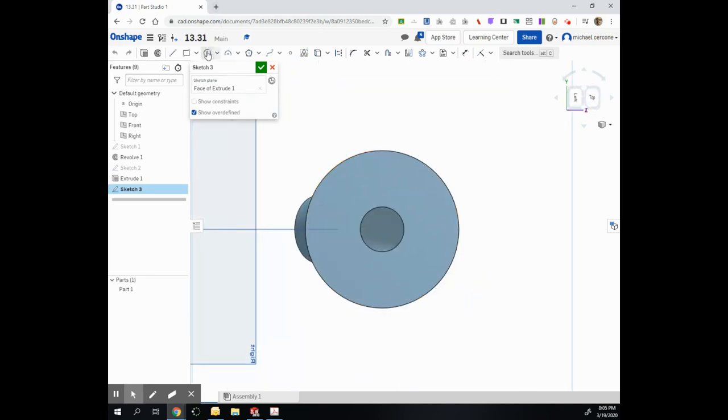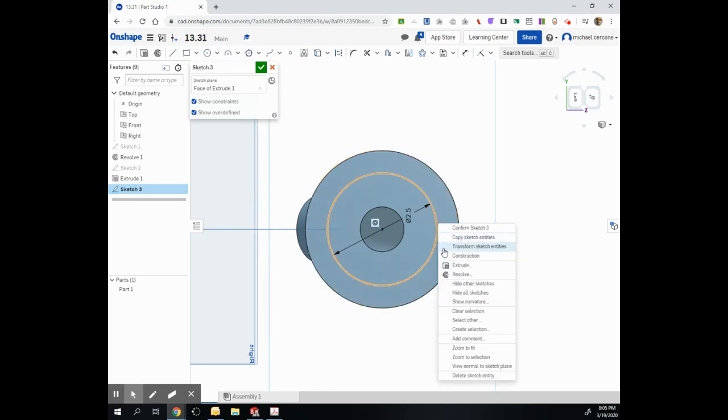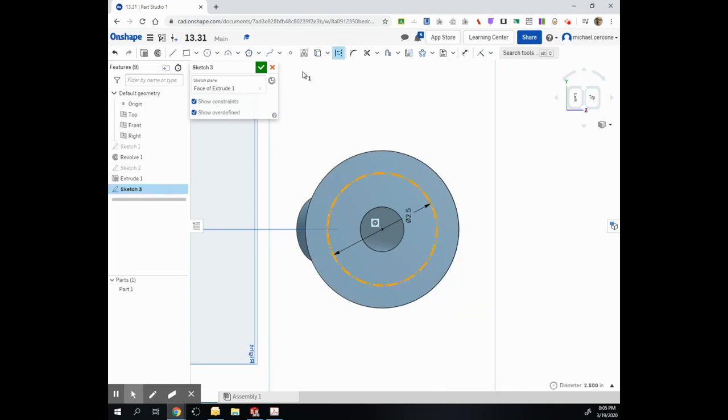So on this one, I'm going to make sure I show my constraints in the beginning, and I will start with the circle. If I hover over, I can get the concentric relation or constraint to appear, drop the circle. Now, you don't have to add your dimension. You could type it in right after you draw it. Now that circle is 2.5. I didn't do anything. You can escape to end the circle tool and right click and add this for construction.